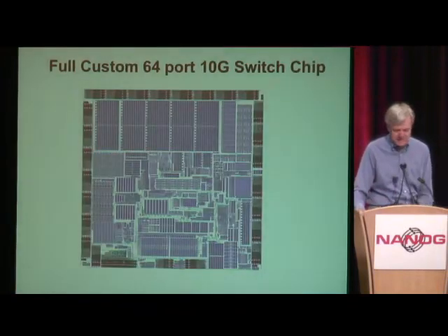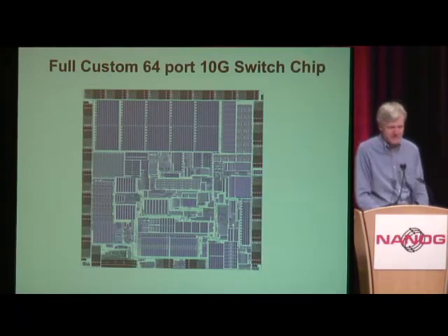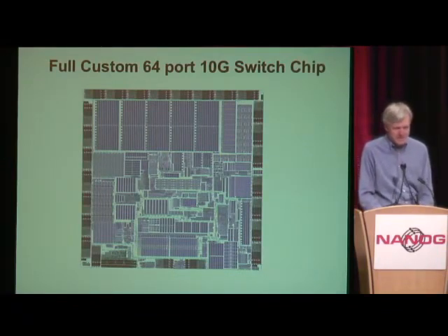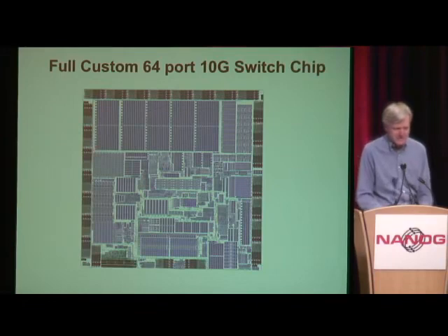And to illustrate this, this is a contemporary 64-port 10 gigabit single chip. You can see it's a very structured design, with big memory arrays for the packet buffers and layer 2, layer 3 tables. In fact, there's very little random logic on these chips. Most of it is just memory.